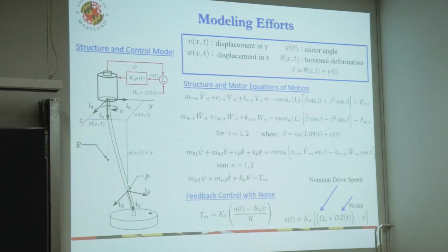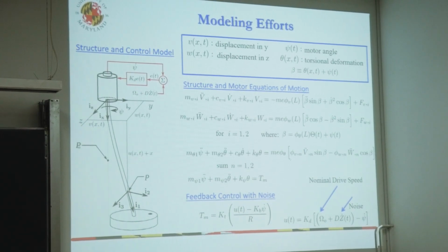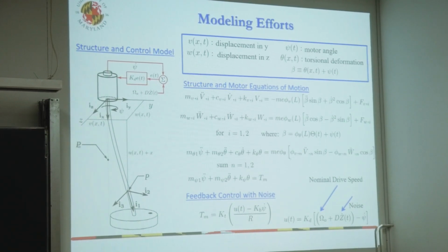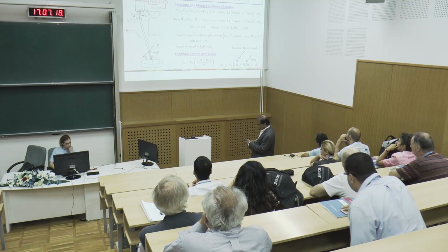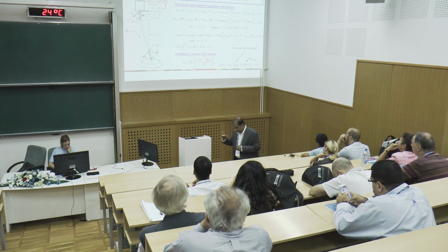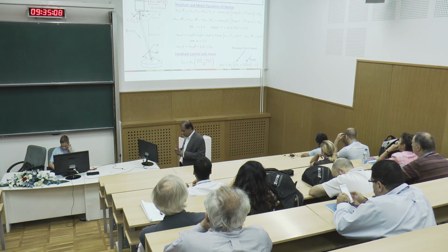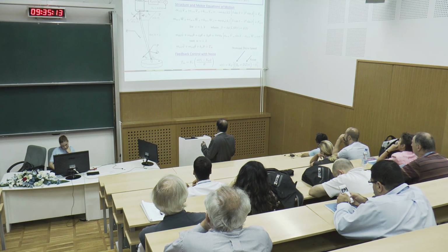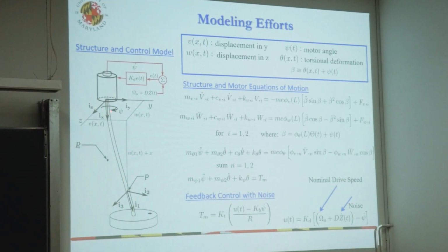We did do some studies to complement the experiments. Essentially, we took the rotor and projected it down to three states: two translational directions, lateral vibrations, and one torsional state, and that led to those equations right here. You also have another equation governing on the top. And then you have your back EMF and other things for the motor accounted for in the loop out here. And the noise is introduced through my torque input into the system.